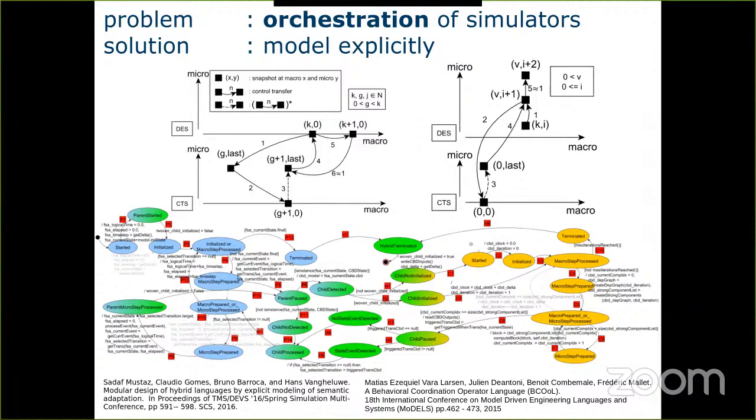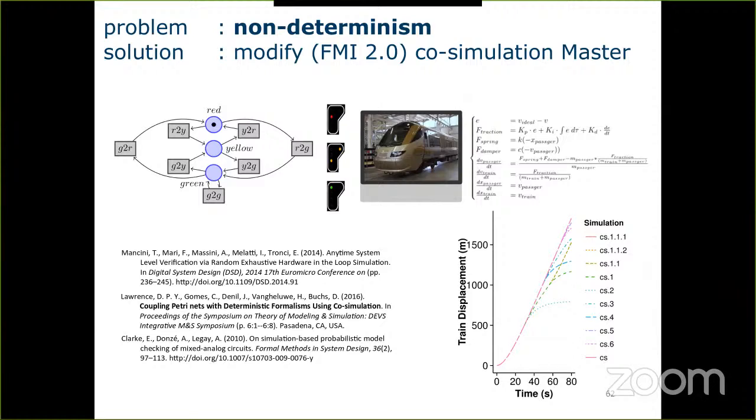And so we will have to somehow combine the stepping of the discrete event, the automaton part, and the continuous time part. And of course, there's a whole theory behind how you can do this correctly. Because of course, in software, we can just do anything at all, but we are actually simulating real systems. So we must get correct results.